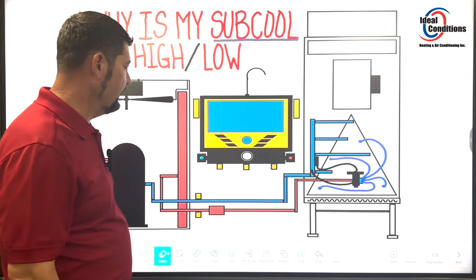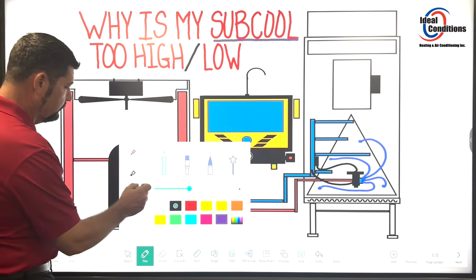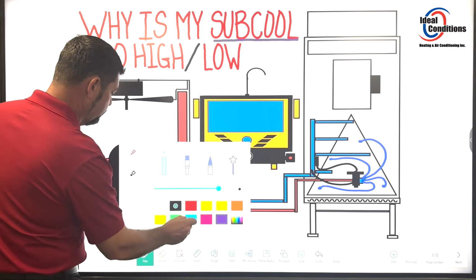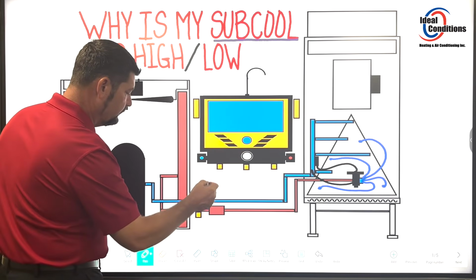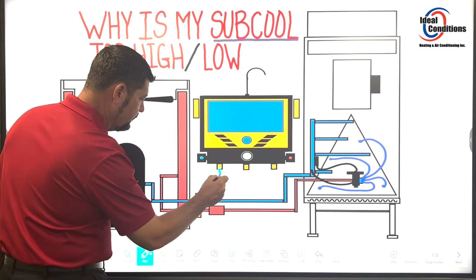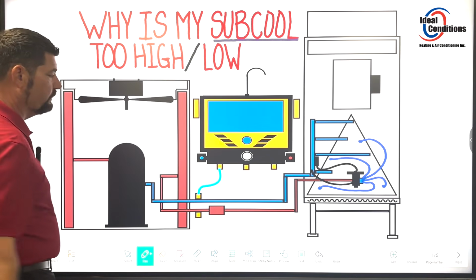So let's look at these gauges here. And let's just go over a couple things here. I'm going to say red. I'm going to say blue. All right, so the low side will be on this left-hand side. We're going to go ahead and just hook that up to our vapor line.